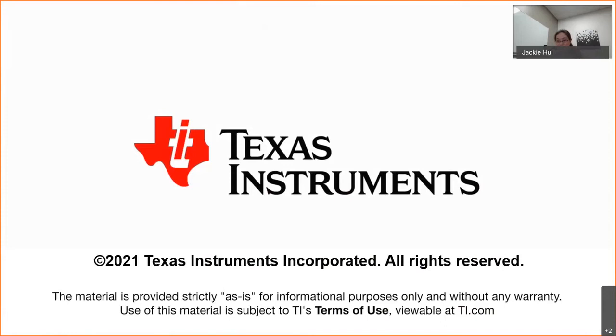Yes, hey Jackie, we got a question from earlier in the presentation, specifically about selecting diodes in the bootstrap. This is asking about high voltage. An example would be a 1000 volt V-bus. The question is, there are not very many high voltage fast recovery diodes in the market. Would it be possible to use multiple diodes in series to block 1000 volts, or what should we pay attention to at such a high voltage application?